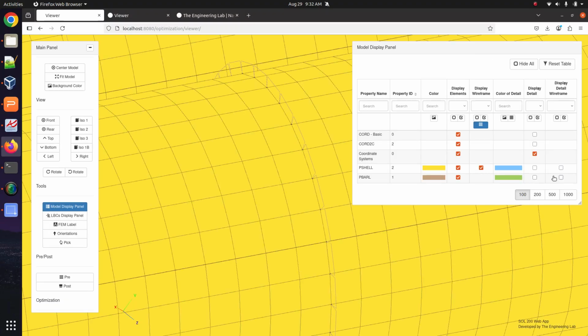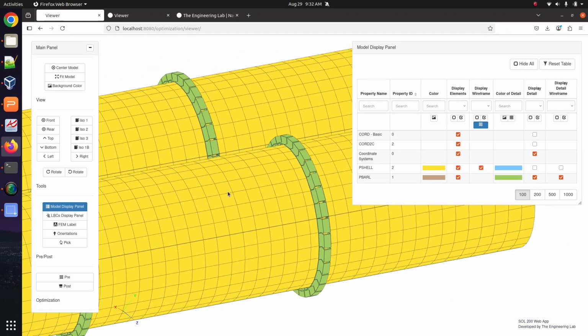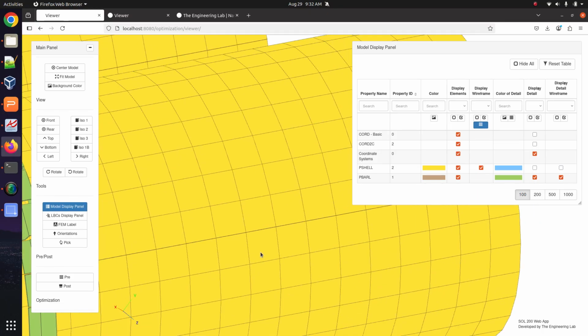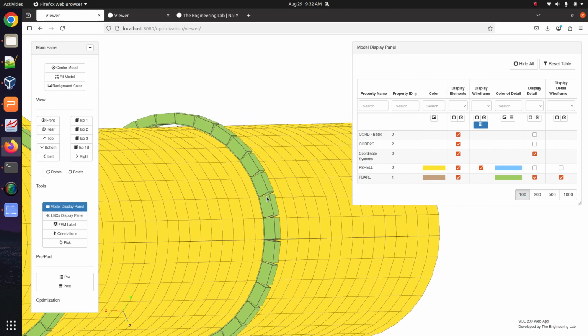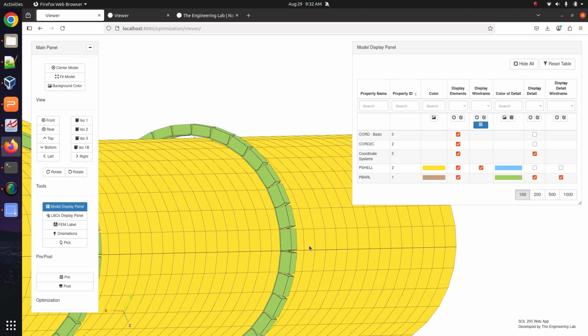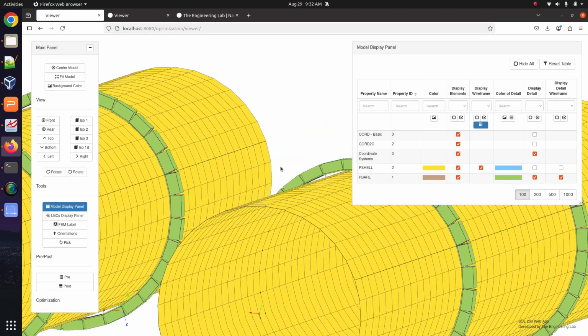What we went ahead and said was, you know what? Rather than me manually specifying the orientation vectors, let's just say this. Point the orientation vectors so that they're perpendicular to the face of the cylindrical wall, or normal to the 2D elements. And that was the result, like you saw here on the screen.